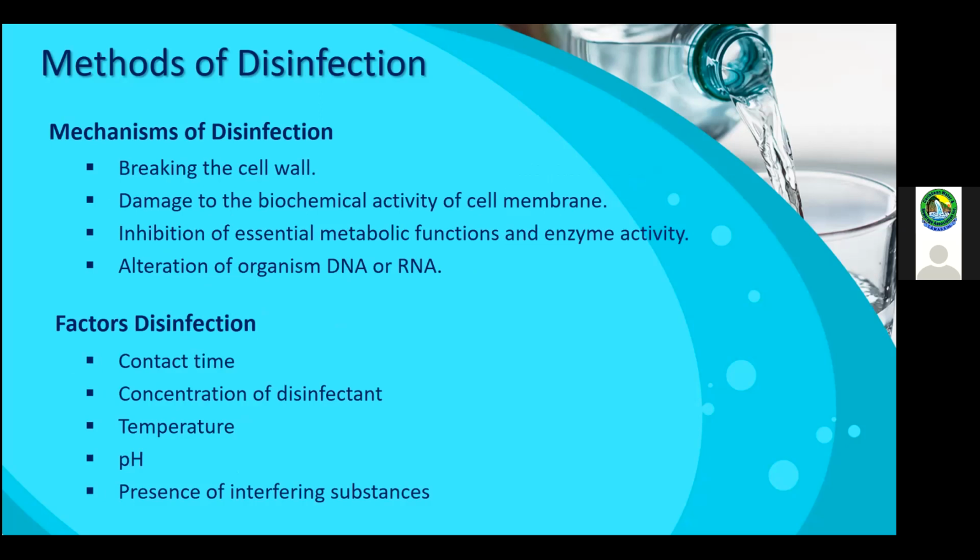So what are the mechanisms of disinfection? How exactly does this take place? Disinfection breaks the cell wall, damages the biochemical activity of your cell membrane, inhibits the essential metabolic functions and enzyme activities, and alters the RNA or DNA.